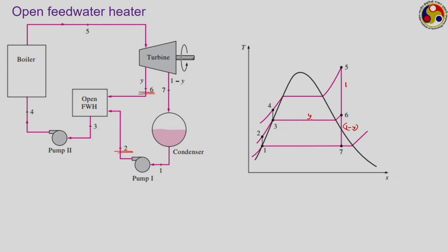And then this y fraction, of course, we are talking about two stages of turbine expansion, but truly speaking it is a single turbine. Just to mention that there are different flow rates, we are referring to as one high pressure stage and another low pressure stage, but it is not like reheating where we have two different turbines. In case of reheaters, we have two different turbines, but here we have the same turbine, but having different flow rates, lower flow rates I should say, on the later stage of expansion.